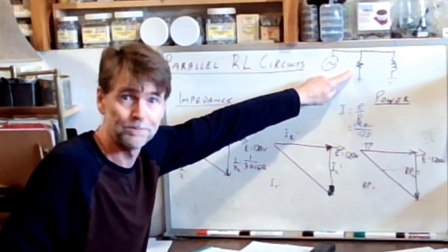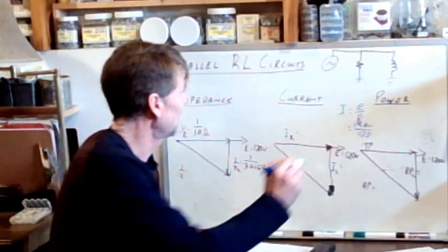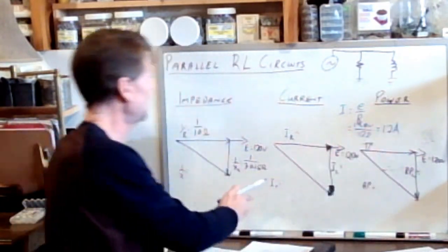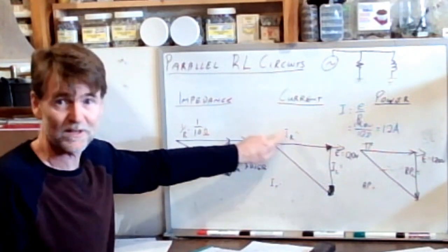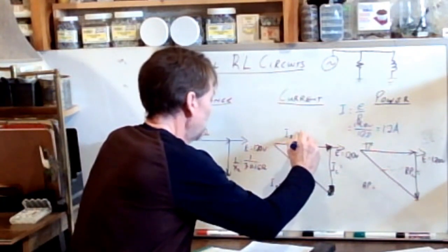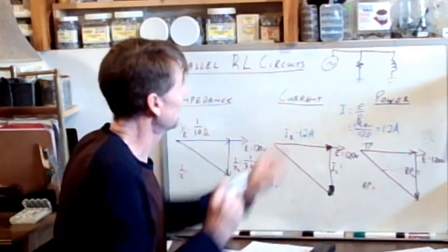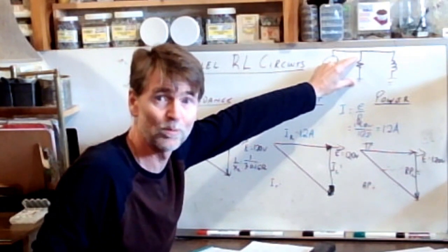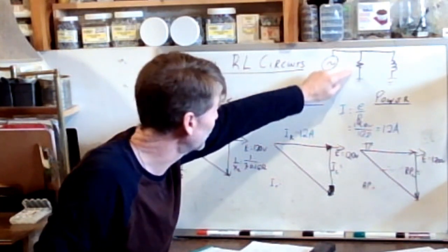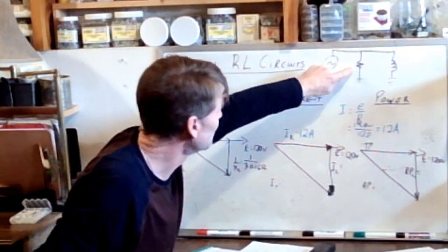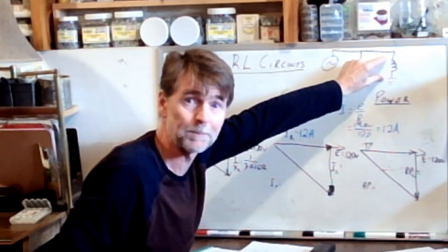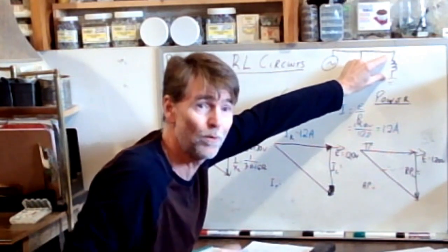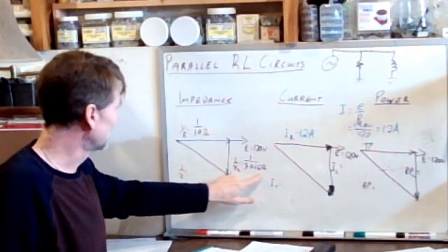Okay, awesome. What does that mean? It means that I equals 12 amps. Okay, so the current through the resistor, I subscript R, is 12 amps. Okay. That's what's happening right there. We have 120 volts, we have a 10 ohm resistor, that means there will be 12 amps flowing through it. Okay? Now we can go out here and we can do the same thing. There's 120 volts dropped across that load, and I know the impedance value of that load. It is